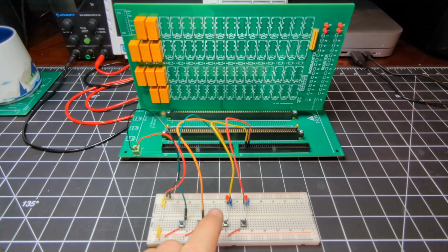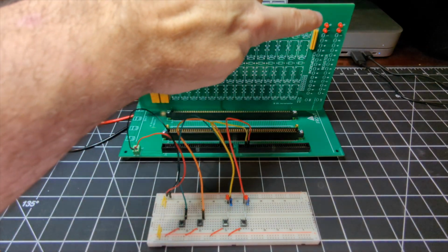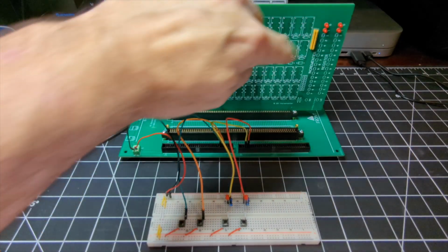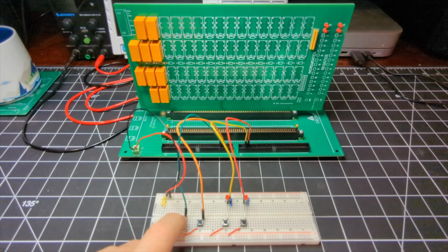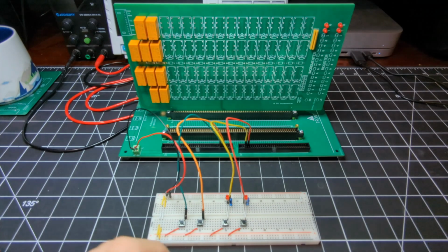All right, so we have the test rig set up. These two buttons and two lights on the right represent the first 2 bits of the address bus. And we only have the first 2 because we only have the first 2 installed in our incrementer. This button represents LIC, which is the load incrementer, and it takes the value from the incrementer and loads it into the internal register. And the SIC is the select of that register onto the address bus.